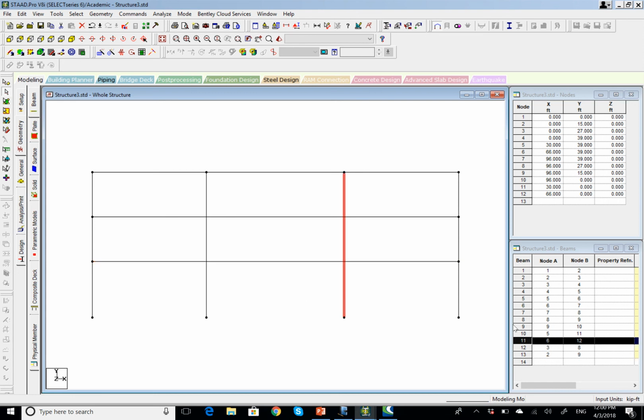The interaction between them, there is no interaction. The software here is going to just feel that there is no interaction between them, although they are connected in real life, right? This is the column and the beam. They are connected together, okay? If you leave it as an entire member like this, the entire horizontal member and the entire vertical member, the software is not feeling the connection between them. You have to break them, okay, at the intersection here.